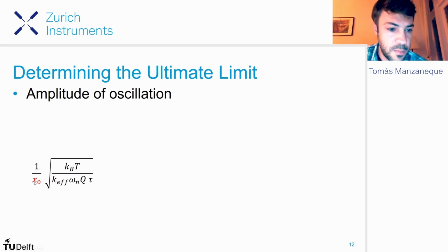And then finally, we have the actuation amplitude here. This means the displacement of the resonator, the harmonic displacement that we set in order to interrogate it. In principle, we see that it's in the denominator, so we should increase this displacement as much as possible, because then we will have a smaller Allan deviation. But of course, there will be a limit for that.